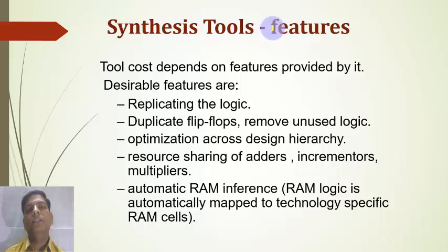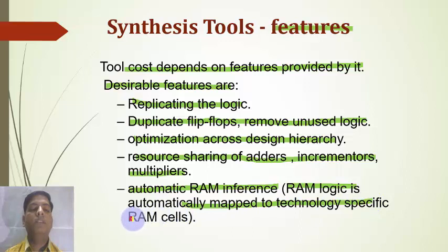Synthesis tool features. Tool cost depends on features provided by it. Desirable features are replicating the logic, duplicate flip-flops, remove unused logic, optimization across design hierarchy, resource sharing of adders, incrementers and multipliers, then automatic RAM inference. RAM logic is automatically mapped to the technology specific RAM cells.